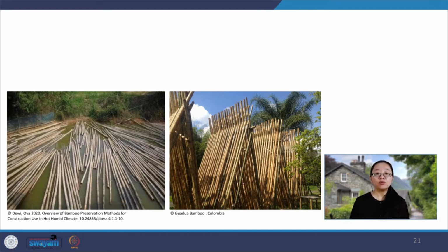In the contemporary world today, treatment of bamboo has developed into several new methods such as microwave drying, injection, preservation by immersion, surface bleaching, and so on. To sum up, to be able to use bamboo as a building material, one must take precautions and treat it before use.